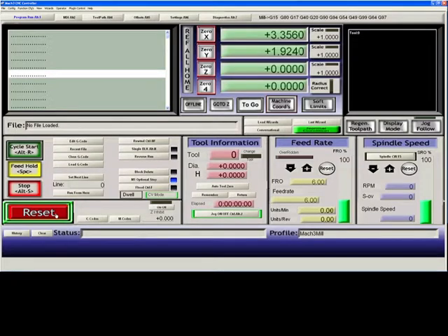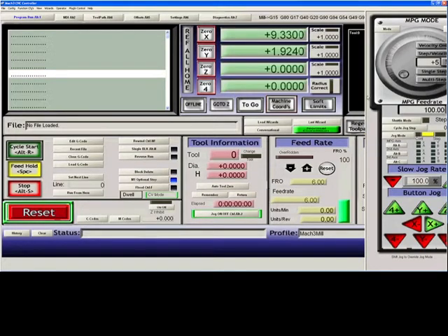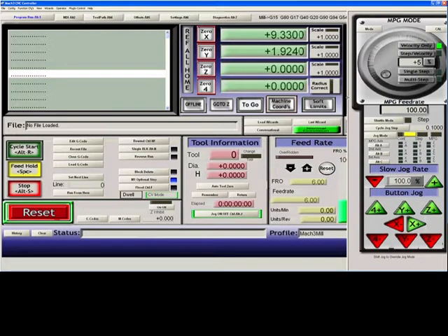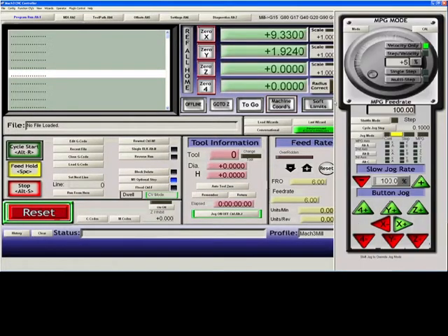Now a secondary complaint is, okay, my motors move, but they move very slowly when I jog. Why would that be? Well, as you can see, if I hit jog, I'm going 120 millimeters per minute on this system. If I hit the tab key to bring out the jog tab, and incidentally, to control the jog tab, drag it out so that it is on your system facing you and you can read it fully, tab it in, tab it back out, and it will remember its location from then on. The jog rate down here at the bottom, you can see it's set to 100% on mine. That can be set to any value, so make sure that it's set to a value that you want it to be for your slow jog.